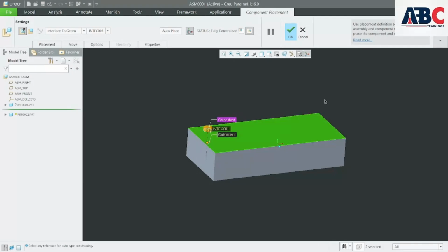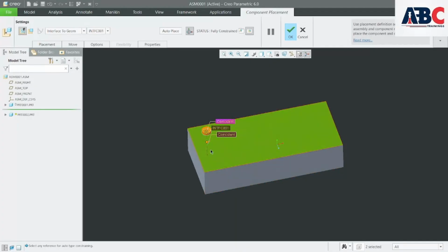see, first of all, I already gave the coincident constraint to this outer part of the surface and to the inner part of this plate circle, right? And another constraint I gave was the below surface coincident with the upper surface of this plate. Now it's showing us okay.